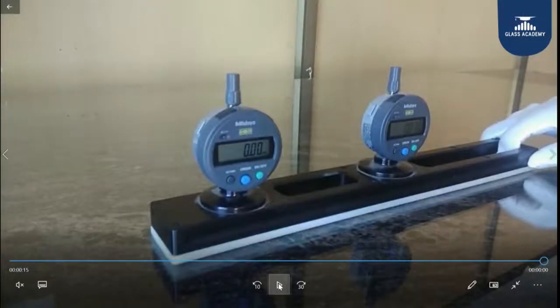So the roller wave is nothing but the glass is moving on rollers and it is going through peaks and valleys. So we need to calculate the summation of the peak and valley. If you see the minimum value, initially it came 0.0 and the maximum value it is showing is 0.07. So the roller wave is nothing but the summation of the peak and the valley. So with the help of the center gauge of the roller wave equipment, we can say that the roller wave in this particular glass is 0.07.